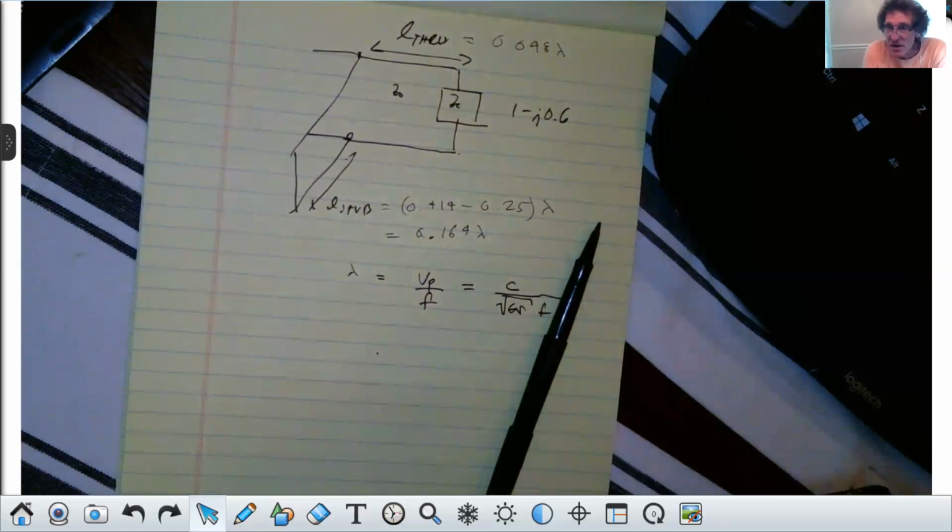And I couldn't understand for the life of me how this could happen. Well, one of the technicians, when he's soldering these things, left a big solder ball on the back side of the coax cable connector. A solder ball at the frequencies we were using, about 1.4 gigahertz, or 1.414 gigahertz, is a massive inductor, and it looked like an inductive impedance, and therefore it messed up everything. Luckily, there was an engineer out there who was available to take a look at the antenna during the test, and he flipped it over and said, "What's this horribly large solder ball there?" And he removed it, and the thing worked.